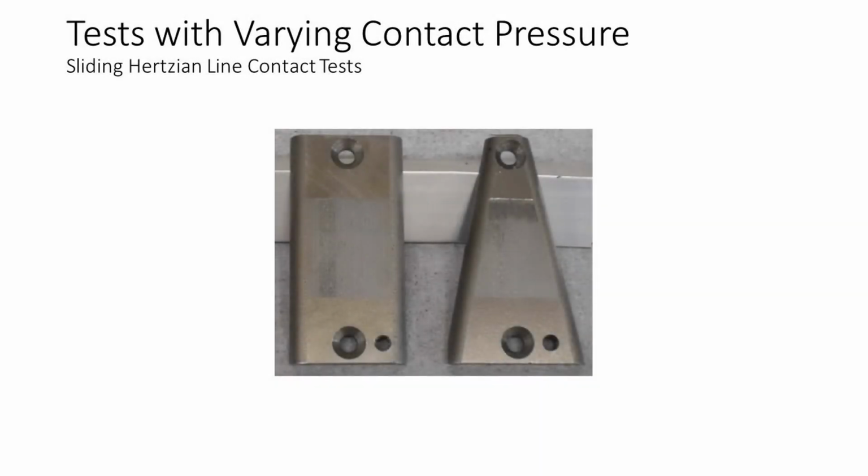It transpires that in terms of RMS and instantaneous friction and contact resistance, with a fully formulated lubricant and these samples, there is minimal difference between the frictional response of the parallel-sided and wedge-shaped specimens. The frictional response appears to be independent of contact width. Visual inspection of the samples indicates that, with a fully formulated lubricant, the wedge specimens scuff at the narrow end. With the parallel sample, a narrow band of adhesive wear is observed, covering the whole stroke length.